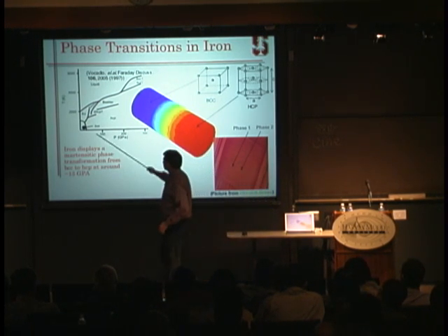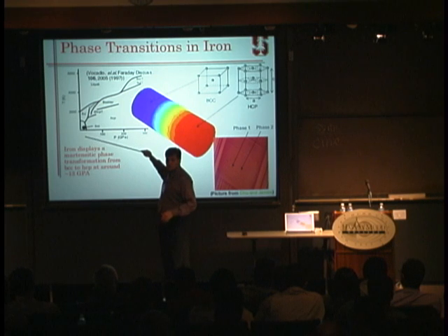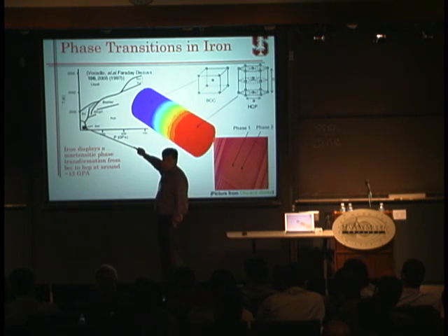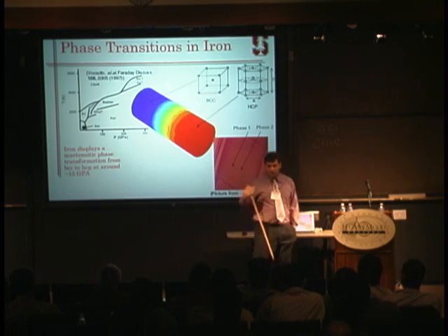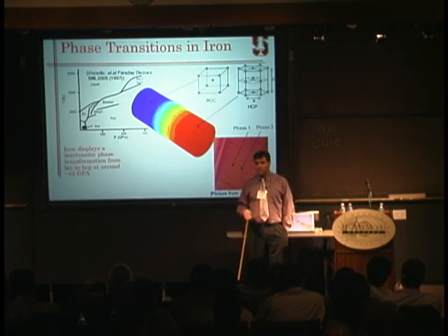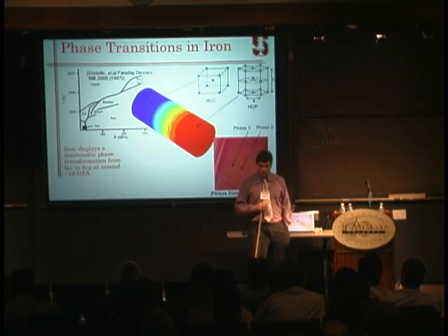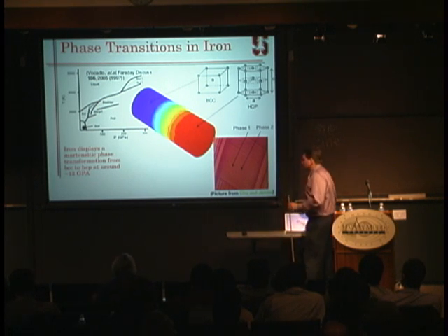So if this is the temperature as a function of pressure, or the TP diagram of the phase diagram of iron. So originally, when you are at low pressure and low temperature, you are at BCC. And if you increase the pressure suddenly, you go to HCP. Okay? Now, this point is not clear what it is. So what I'm going to show you is that based on the computations that we have, there is a reason why it's not clear, because this pressure is very sensitive to very small changes in the type of loading that you have. Okay, and we're going to do that building the best model of iron ever yet done.